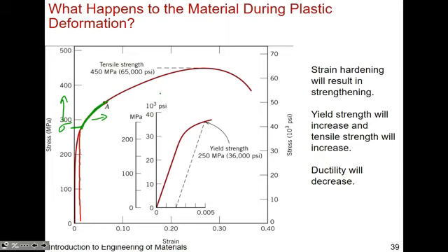So we'll switch roles. First, you're going to plastically deform the copper rod by bending it, let's say. Okay, you're applying some force. Obviously, this is not dog bone, nor is this the standard by any means. So what Zachary has done is he's introduced a whole bunch of dislocations by working this material. So he's increased the strength. How much so can Ethan undo that strength?